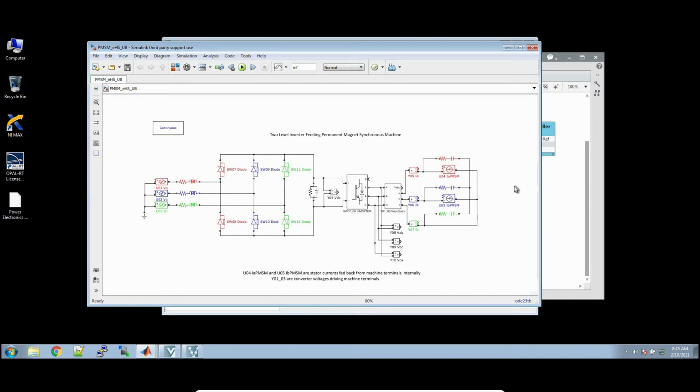If you want a more detailed explanation about how this works, at the end of the presentation I have the Power Electronics wiki linked, and it goes into greater detail as to how exactly all of this works together. But the highlight is that this circuit will be loaded into the FPGA beside the PMSM motor model, and then we'll use this circuit to drive the motor and control it.